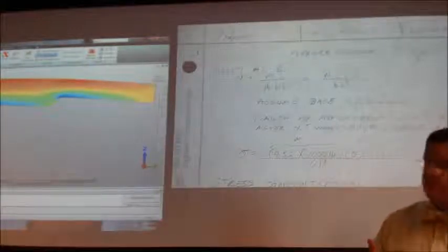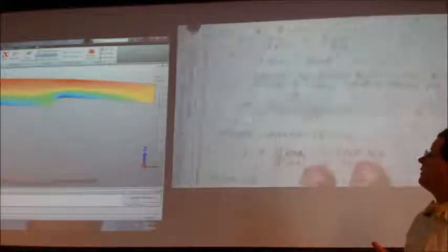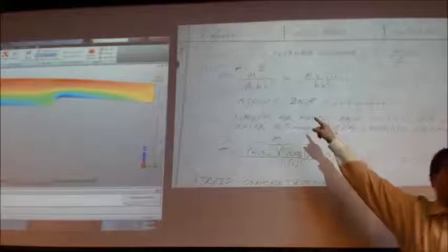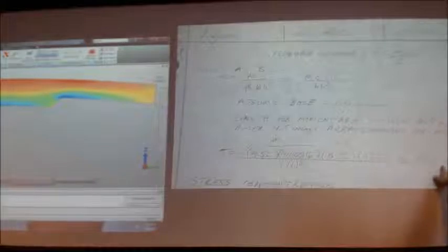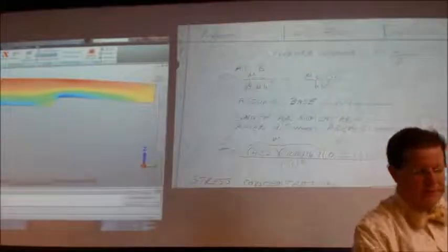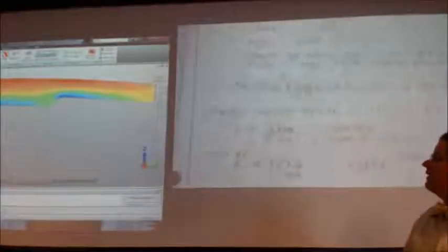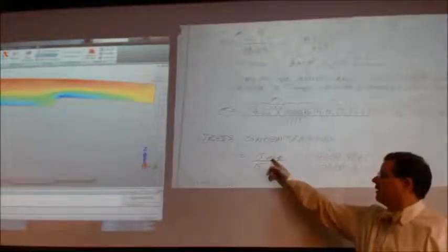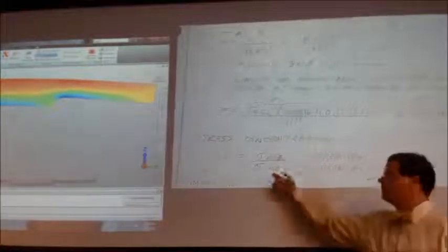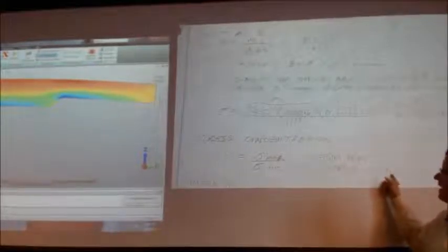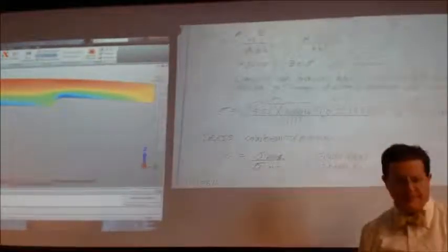So if we calculate our stress at the 4.5, the 12 is the 1/12 base. Okay. So we get a value of 27,000 psi at 4.5 inches from the end. So the way that we calculate our stress concentration is our sigma max over our sigma average. Sigma max is going to come from our model, and sigma average from our flexure, so that's our 27.